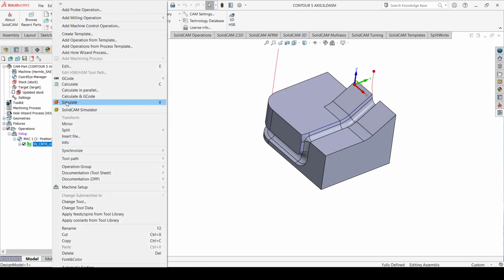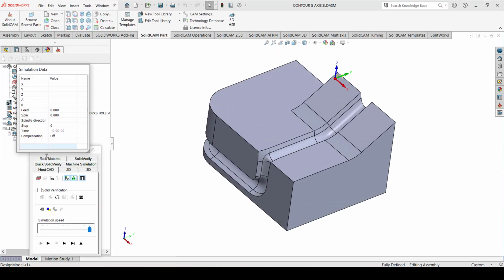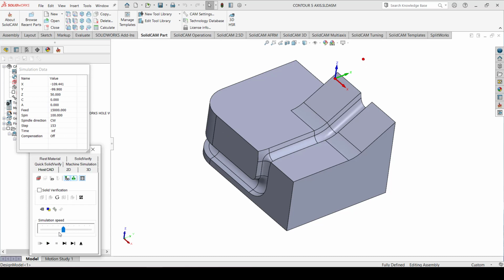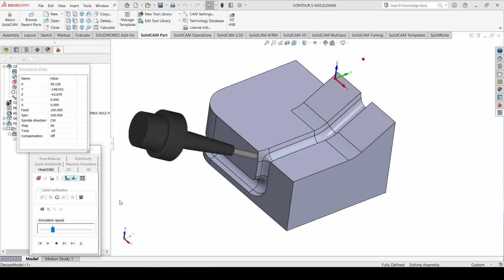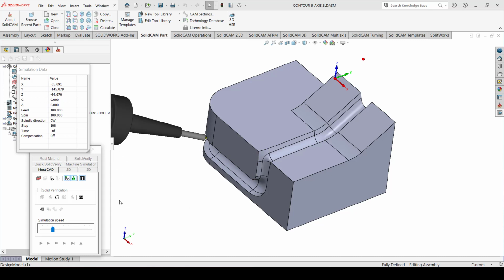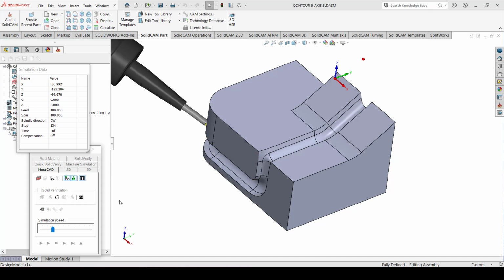And if you run the simulation, this is how it's going to look. Let's reduce the speed. It just follows the curve, nothing else. It follows the curve, and the orientation lines determine the tool axis direction. So you can see that you can do a very nice tool path here to do the chamfer of a particular part.